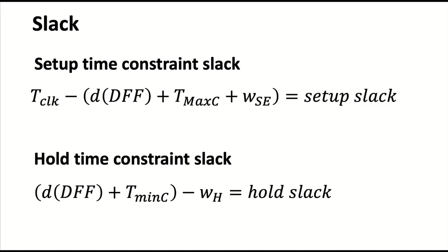Yes? That's what it would mean, yeah. That means you have to fix it. Yeah, so you don't want it to be negative. Well, you don't know. Might not. Those flip-flops might not get the correct value. Right? Your logic might not settle in time.